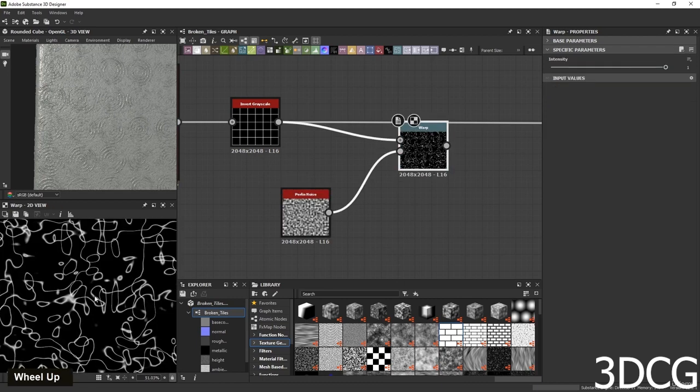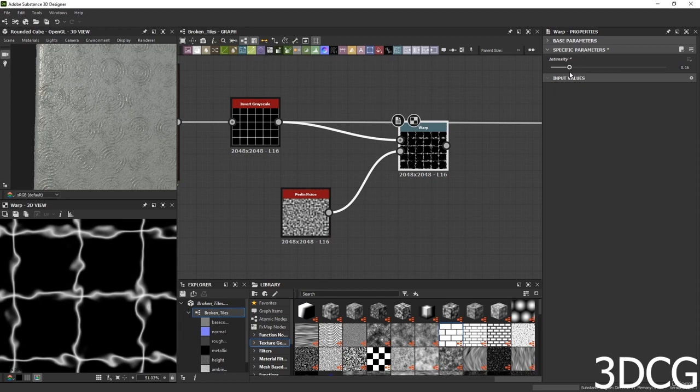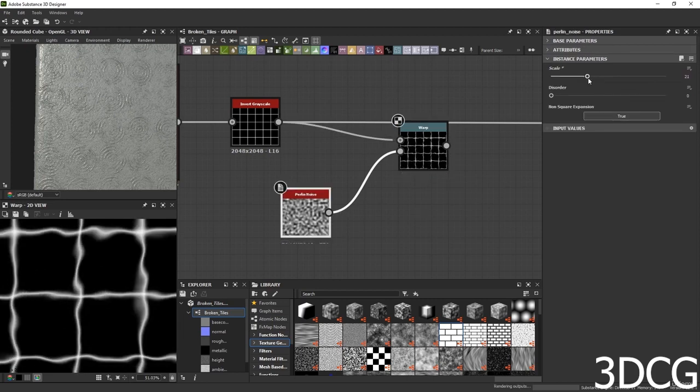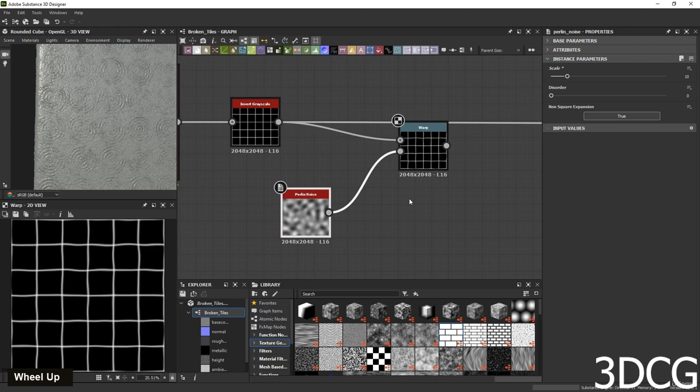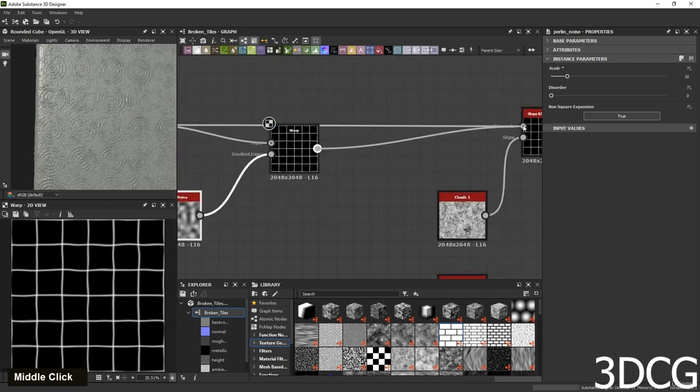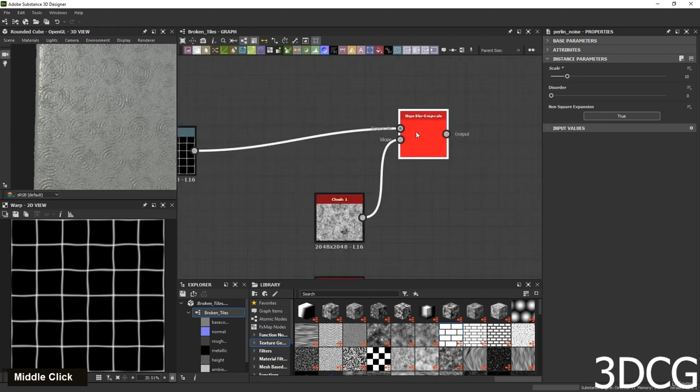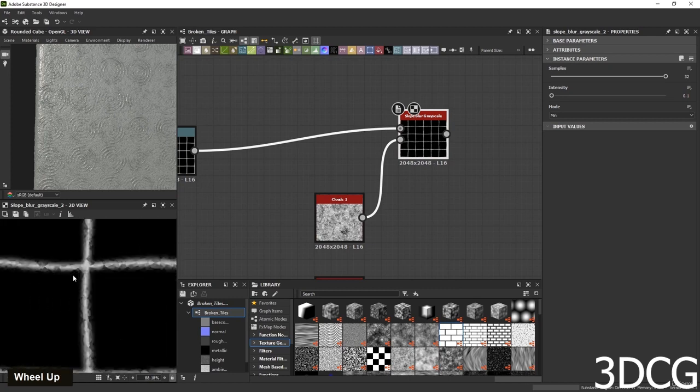And it's gonna warp the shape based on input value and also the intensity, the only option it has. So drop the intensity, one click on Perlin, and drop the Perlin noise scale. All right, now feed that to slope blur. Right, now we have something like this.